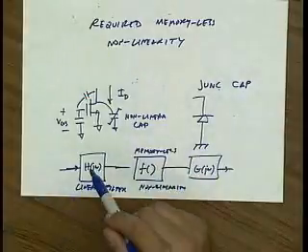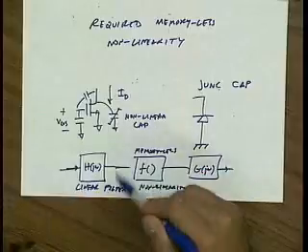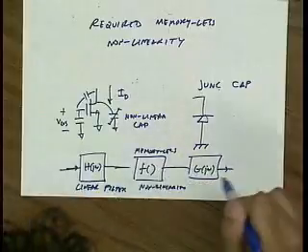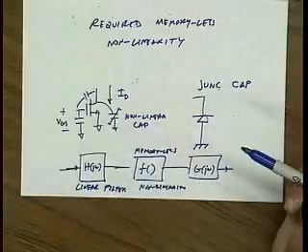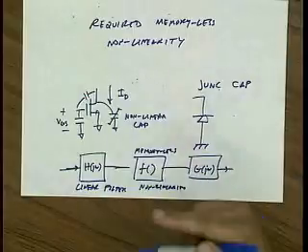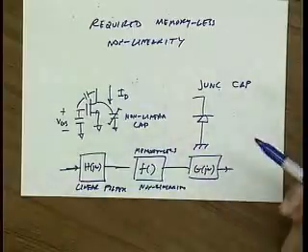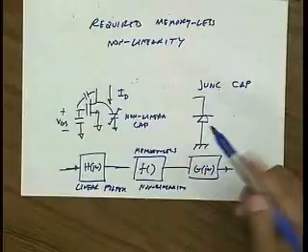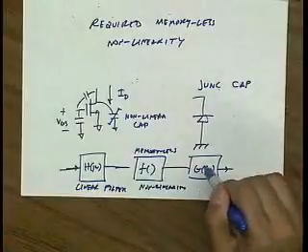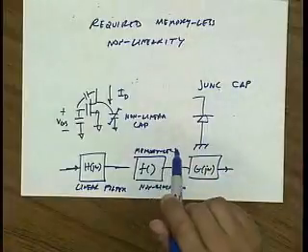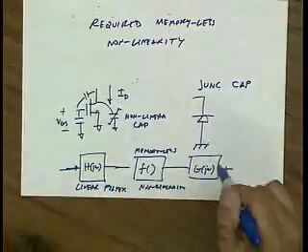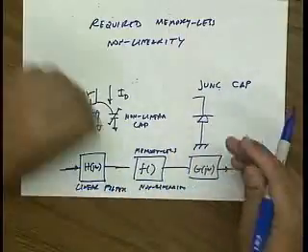So if I come in with a two-tone and then I apply it to some memoryless nonlinearity, the output will have third harmonic, fifth harmonic, second harmonic, all the intermodulation products. Well, the harmonics will get attenuated by this filter. The intermodulation terms, the ones that fall in band, into the passband of the amplifier, will not.